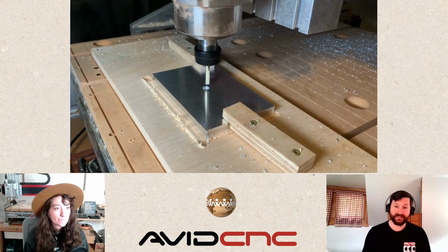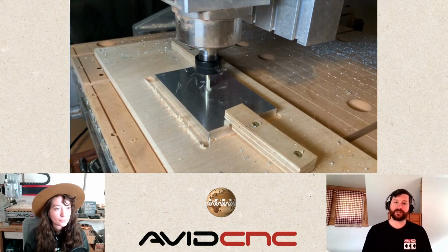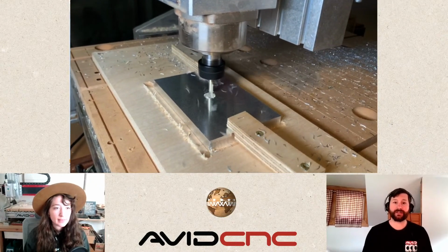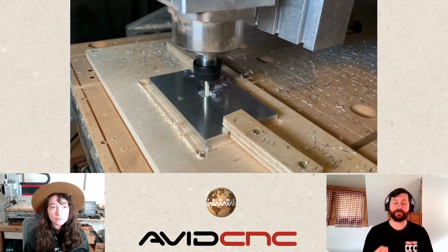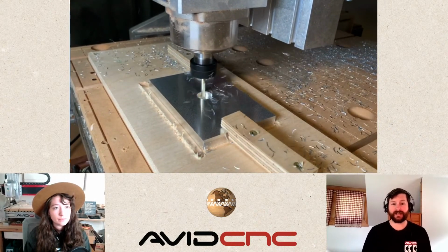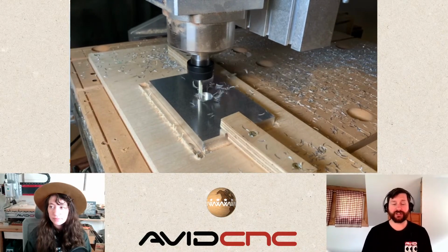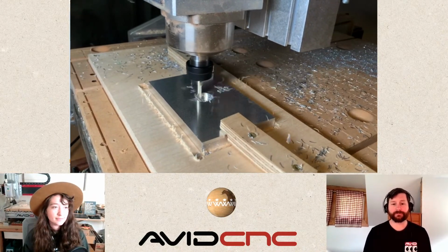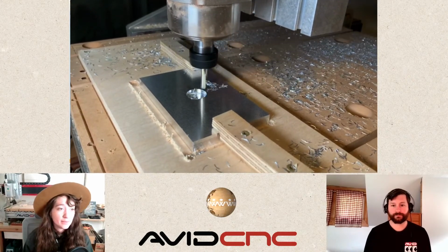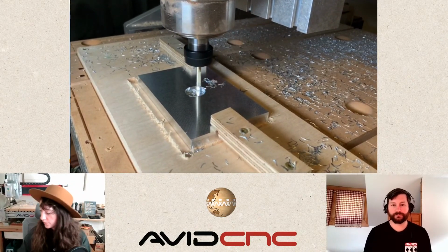These lateral moves as we plunge down into the material are one of the biggest takeaways if you want to machine aluminum accurately with a router. We need to have that lateral movement as we go into the material, and you can see here exactly why. It's because it allows those chips to get out and away from our tooling. Look at those chips. Those chips came out perfectly, really nice, and I was really happy with the results of that.